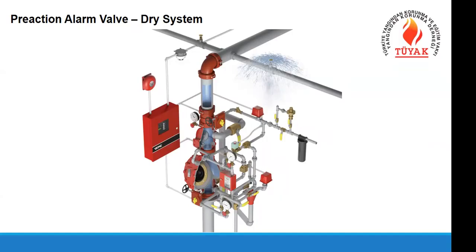So it gives you information that there is a problem at first, and if one of the systems, like detectors or sprinklers, has not operated, it will not release water inside the room. So this is a pre-action alarm valve system. It is in general also used in cold storage rooms that require dry systems.